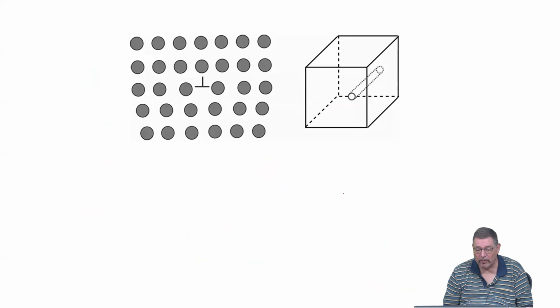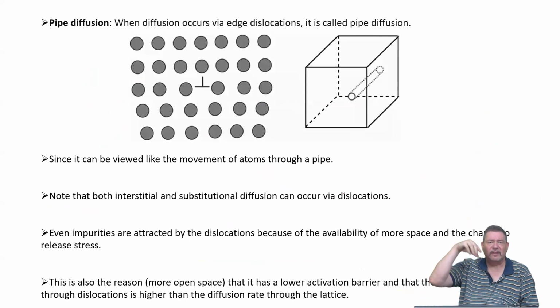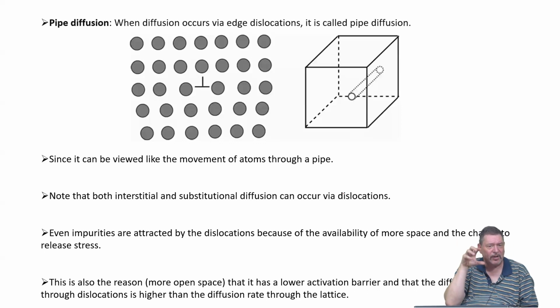And the same is true for dislocation diffusion. When we talk about dislocation diffusion, we call it pipe diffusion, because dislocation diffusion could also be misunderstood as how the dislocation migrates. But here it's meant how single atoms diffuse along the dislocation core. Since the dislocation core is thought of, and I think many experiments have verified, like a pipe. It has a distorted region which has a radius of about a lattice constant or so, where the excess volume would be higher. So diffusion is then taking place preferentially along the dislocation core.